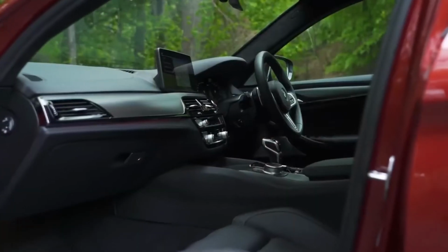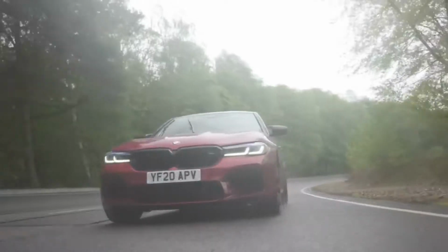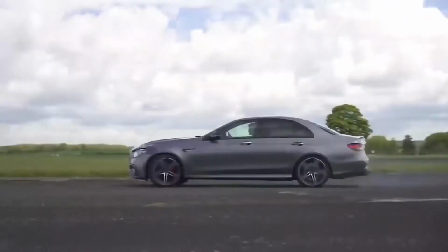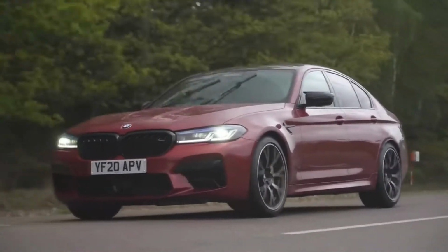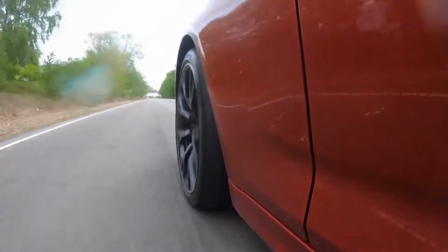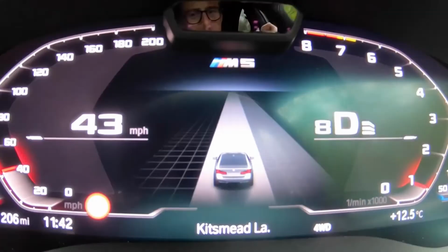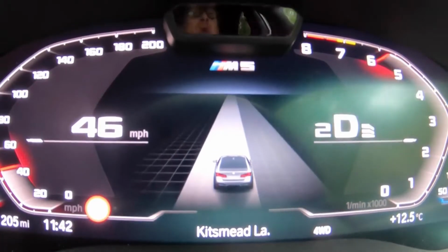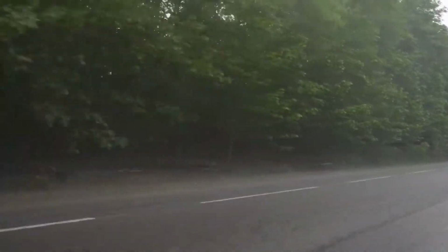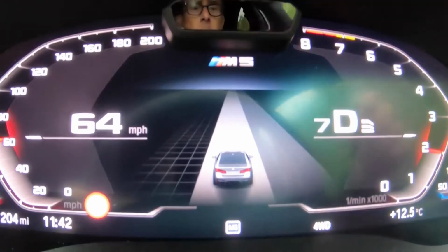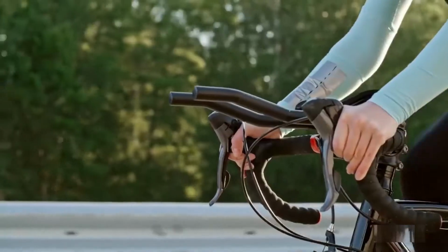Engine delay and kickdown. Now, let's get out on the road and look at everyday driving. When you're driving on roads where there's 80 kilometers an hour as a speed limit, or 50 miles per hour, then you suddenly need to overtake someone, for example. You floor the accelerator and you may notice some engine delay, and it may take a while for your car to start accelerating. This is because when you're cruising at 80 kilometers an hour, your car runs on a high gear.